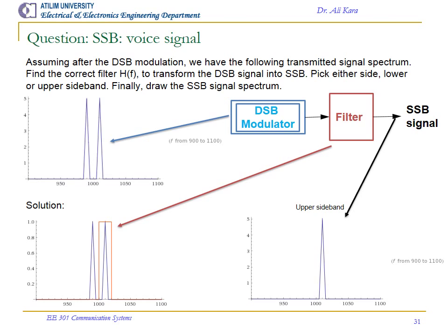Solution: note that voice signals in baseband start from a low frequency but not zero, and end at some intermediate frequency level. This sort of signal spectrum is effectively suitable for SSB modulation because one sideband is separated from the other by a reasonable gap.